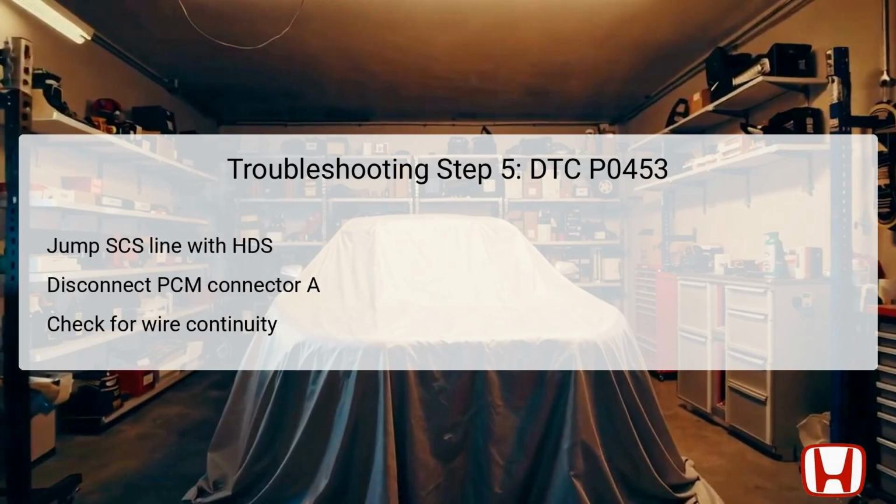If continuity stands confirmed, it concludes that the P-tank wire is functioning correctly. If issues persist, further inspection and repairs to the circuit between the PCM and the FTP sensor will be necessary, resolving the underlying fault leading to DTC P0453.